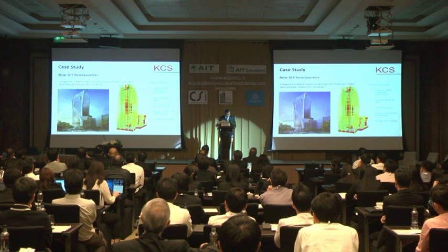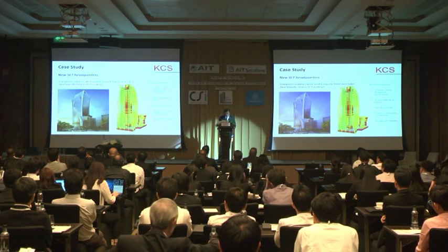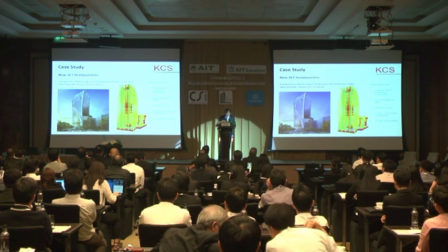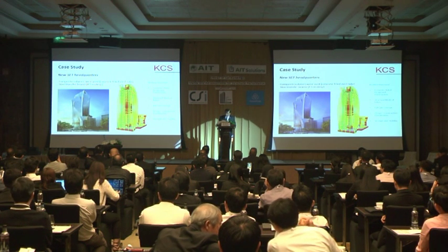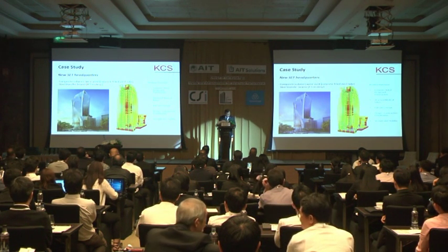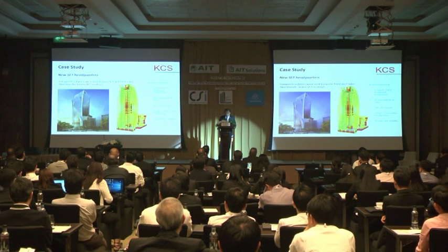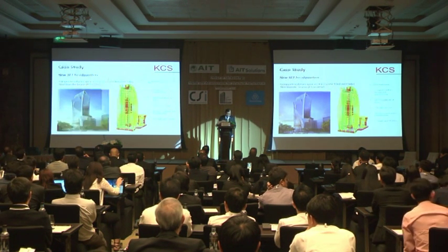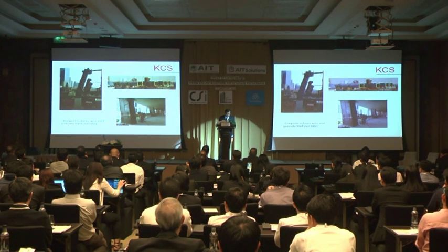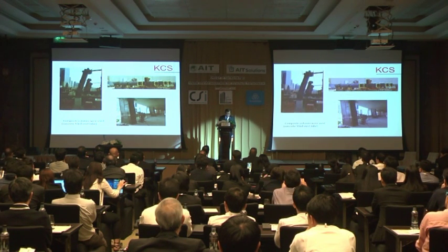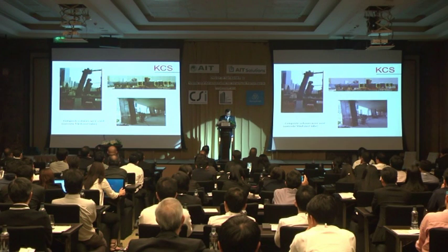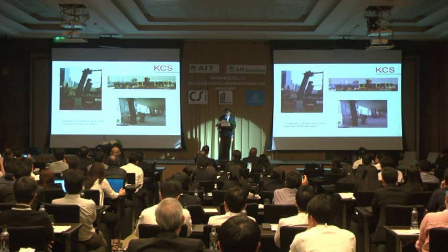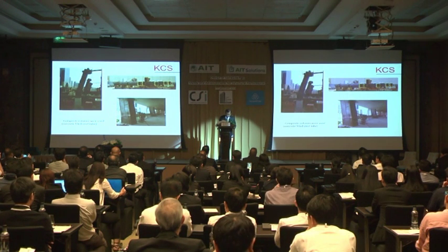Composite columns were used to ensure ductility for strength and stability, as well as to prevent snap buckling and ensure a fail-safe concept. Prefabricated steel tube columns allow ease of column installation and precision in fabrication.